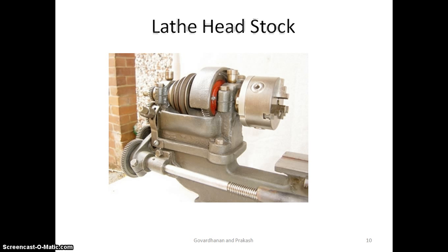The tailstock can be moved along the bed for supporting different workpiece lengths and can be fixed at any position along the bed. The tailstock can also hold metal cutting tools, and can be used for performing operations such as drilling, reaming, tapping, countersinking, etc.